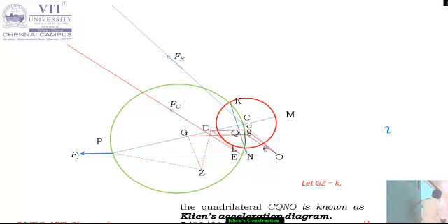So now what you have to do, you have already drawn one line, that is the inertia force. Draw one line which makes 90 degrees to this line, which will meet the point I. Okay, check this. We have to draw one line which makes 90 degrees, so that it meets I and also crosses X. Okay, and you have to draw one more horizontal line to find out the vertical distance.